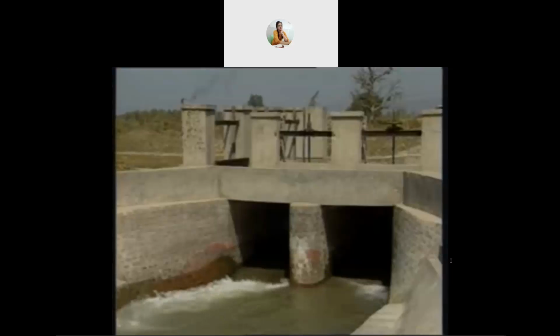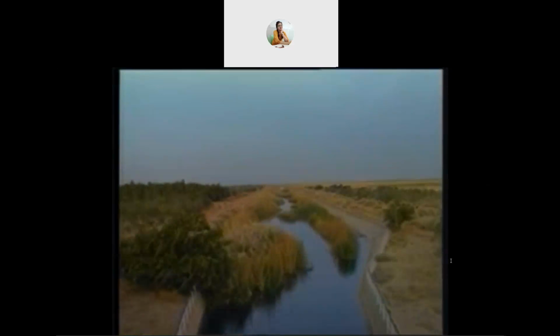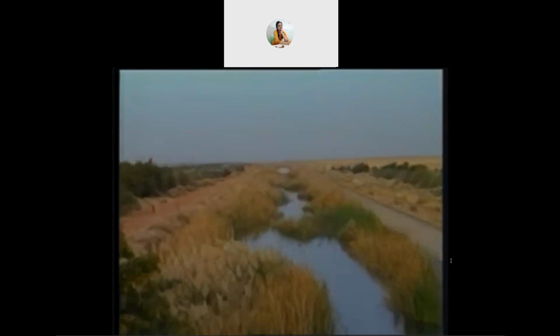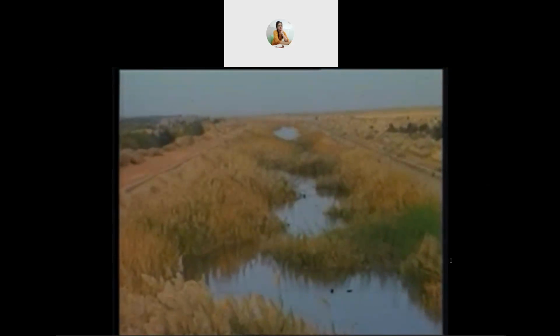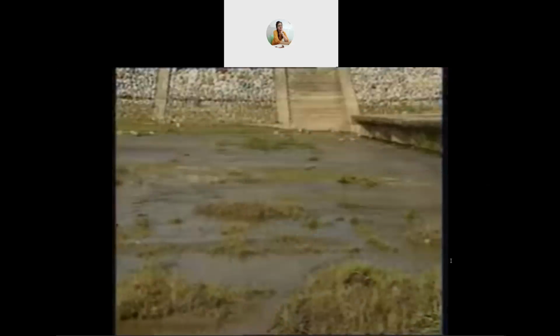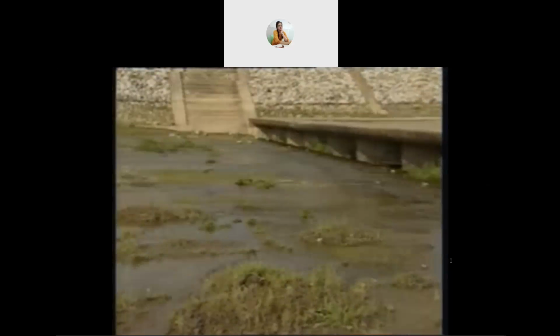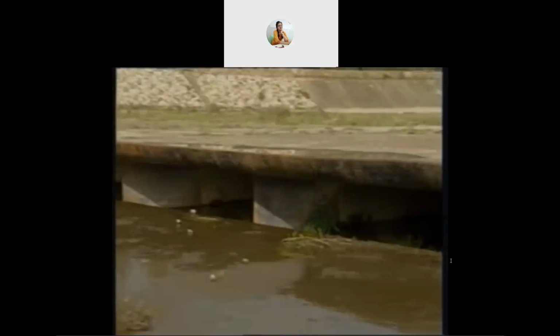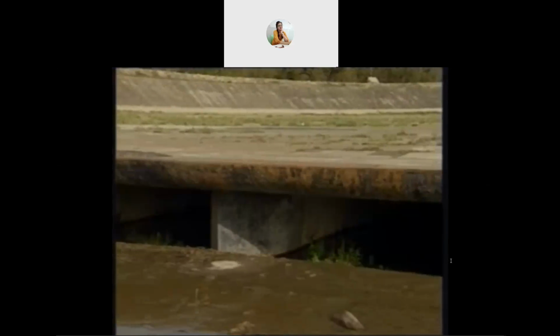In spite of regulation, the irrigation channels do not always draw their desired discharges because of silt deposition, which makes the channel shallow. Therefore, the success of an irrigation project also depends on control of silt and weed roots. In a canal, silt is removed through a silt ejector, which is constructed in the head reach of the canal, a little downstream from the offtake.